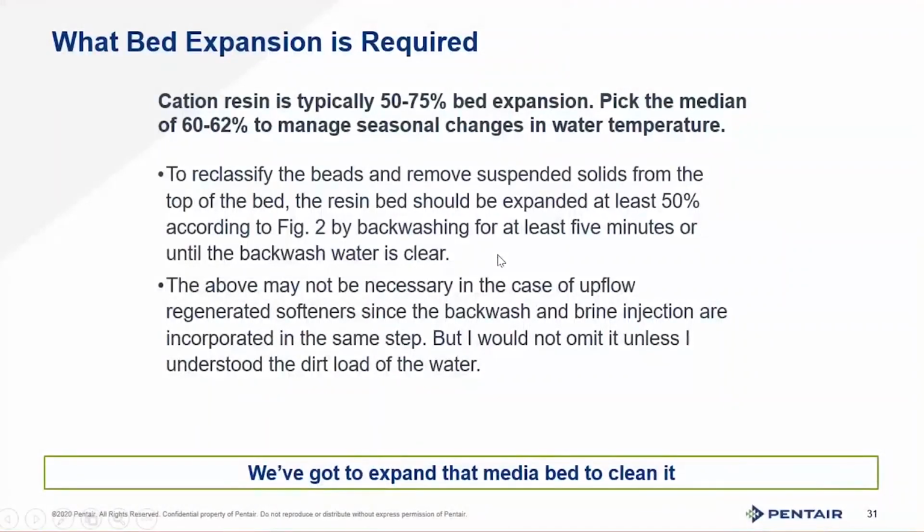Now, backwashing. We've got to do the dishes. We've got to clean up the resin. Why? Dirt coating the resin prevents exchange sites from having access to the water. It's literally coating that resin with sludge that prevents it from interacting with the water. Okay?